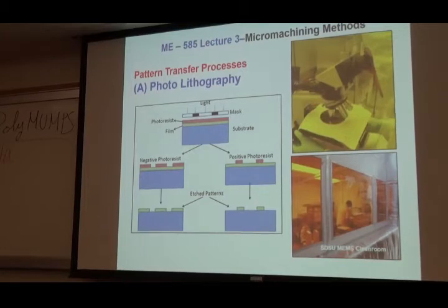However, there is another thing, some of you may have taken this. Those of you who are interested, the minimum expectation I want you to know is SU-8 and Shipley. But there is another photoresist called Futurrex. When you come to the nanofab, your trainers are going to mention this. It's called Futurrex. That's a negative resist. Every time you want to do metal, this is what we typically use. Almost all labs have that. And there is a reason. I'll explain that down the line.